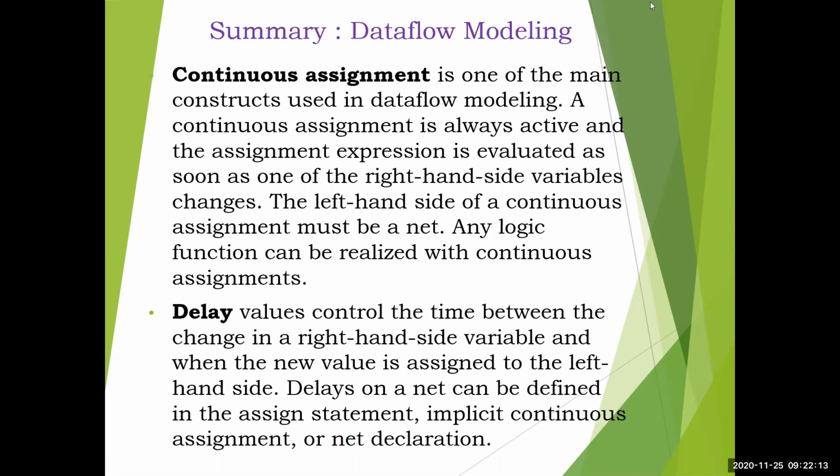A continuous assignment is always active, and the assignment expression is evaluated as soon as one of the right hand side variables changes its value. The left hand side of a continuous assignment must always be a net, and any logic function can be realized with continuous assignments. The keyword is assign.